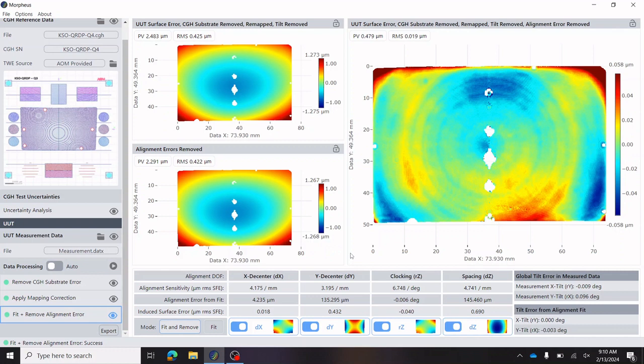This is not utilizing other methods to fit the error. Thus, in general, this method is highly specific and highly accurate. We can notice at the misalignment modes below that for each mode, there's a small map showing the exact figure error that arises from that misalignment geometry. Each of these maps are what are fit to our data.